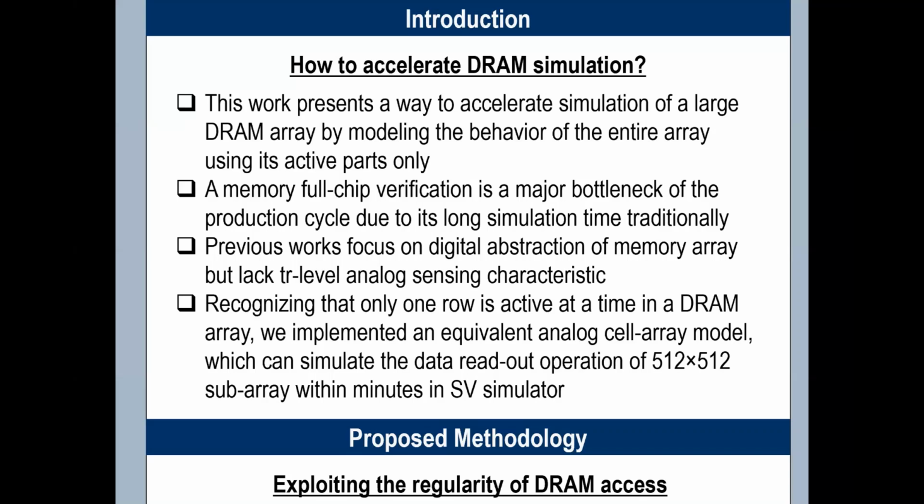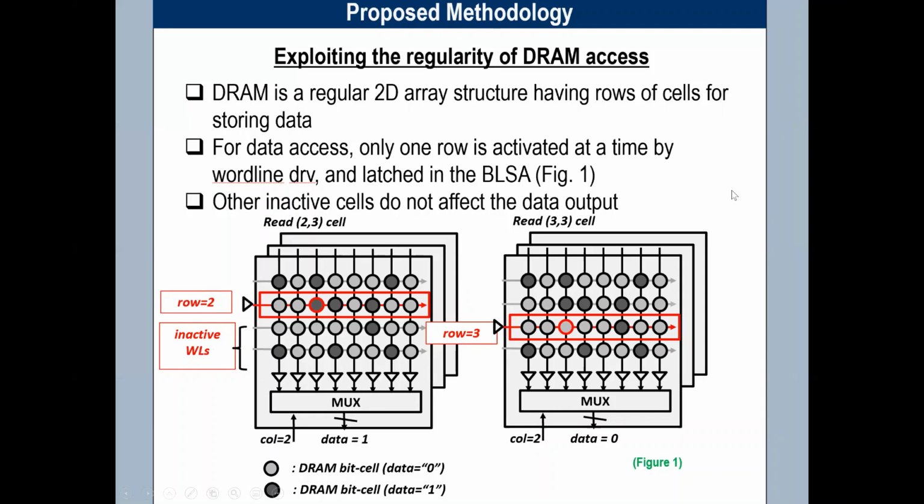So in this work, recognizing that only one row is active at a time in a DRAM array, we implemented an equivalent array model that can simulate data readout faster, within a minute, in a conventional SystemVerilog simulator. Here's our proposed methodology to improve DRAM simulation speed.